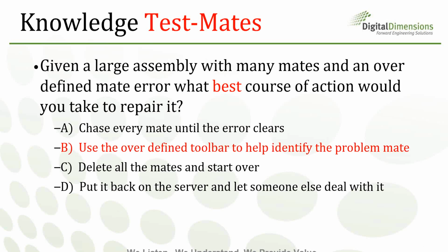Now A, yes, you could do that, but it would be very time consuming, a lot of extra work on your part. The other answer that's actually a potential answer, but not the best answer, is delete all mates and start over, which I wouldn't recommend, but in some cases that is actually a tip that SolidWorks gives on their actual help website that I saw. If you get into a really hairy, sticky situation, that may be required, but you don't want to go there unless you absolutely have to.